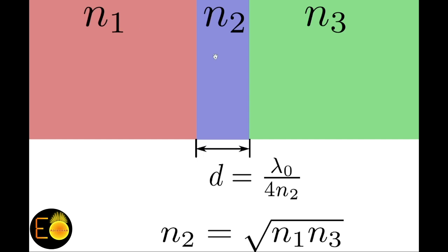In this case, I will show you that at normal incidence the entire power will be transmitted to the third layer, and as the angle varies, the reflection also will increase. But I want to observe the same thing by varying the width of this middle layer, that means D. I want to study what happens if I change this dimension. The standard theory states that the dimension, in order to get full absorption, must be expressed by this particular factor. Now I want to study what will happen if I change this dimension gradually from less than the theoretical value to greater than the theoretical value.